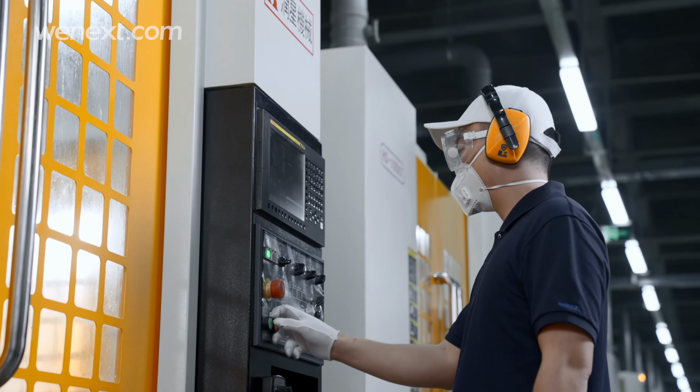If you have a limited budget, or the surface of a part is the only position that needs to be machined, 3-axis is the best choice. The setup time for machining is much shorter than 4-axis or 5-axis, and the processing price is much more affordable. As 3-axis is easier to program, the maintenance fee is much lower.